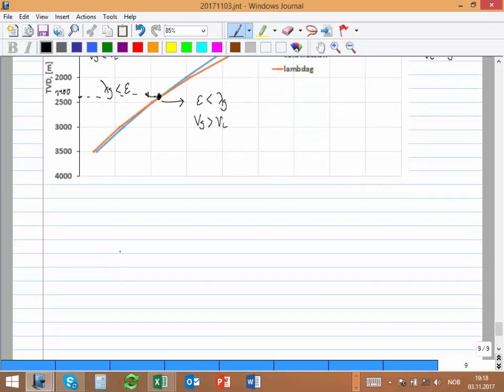So let's see the home exercise that you have to deliver. You have to deliver exactly what we have done so far, but now you also have to do a case 2. In case 2, you do the calculations the opposite way. You have PWF equal 200 bar, Q oil again 1,000 standard barrels per day, and I want you to calculate how much is PWH. So I start from the bottom and I have to move up.